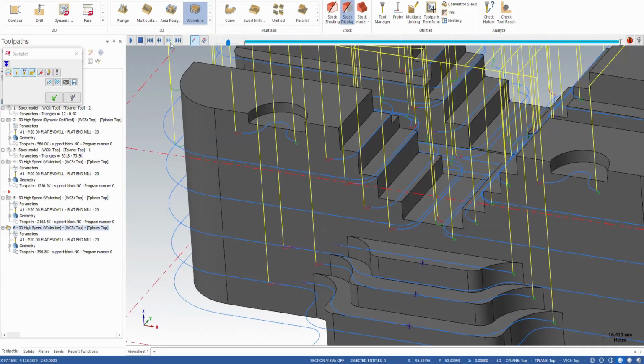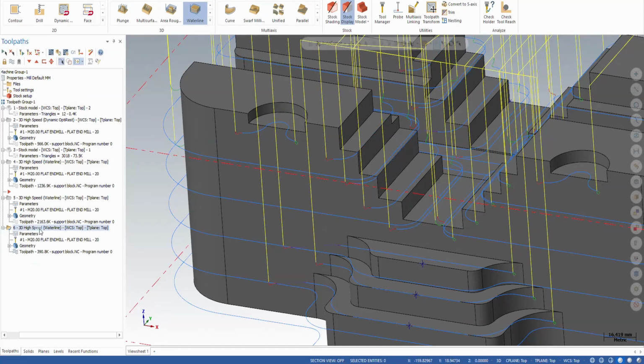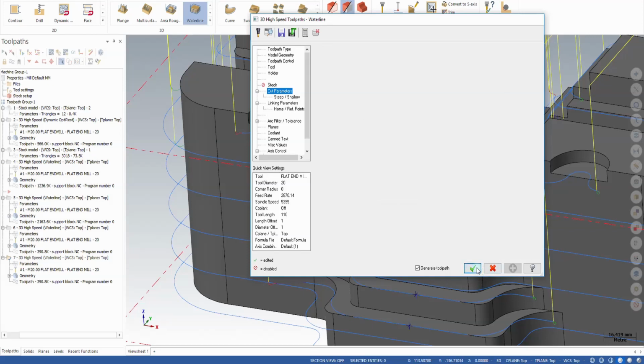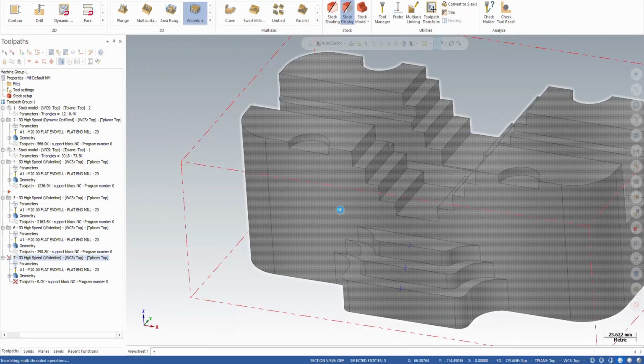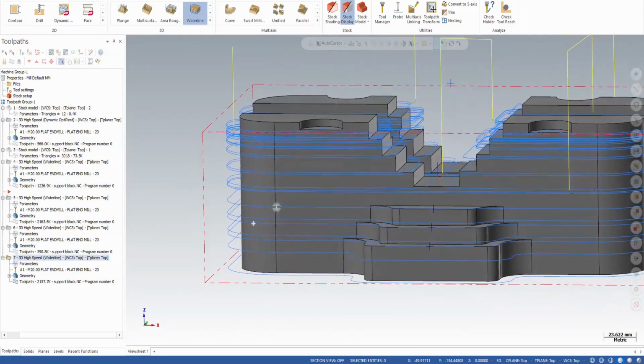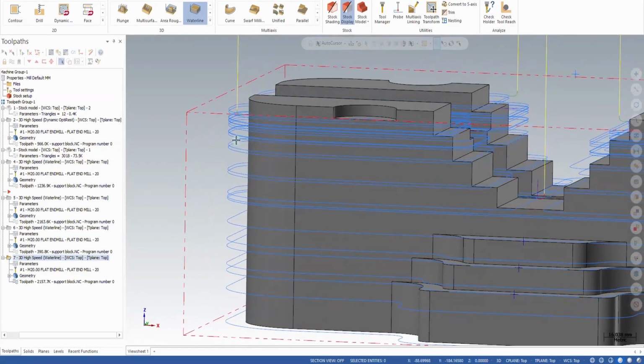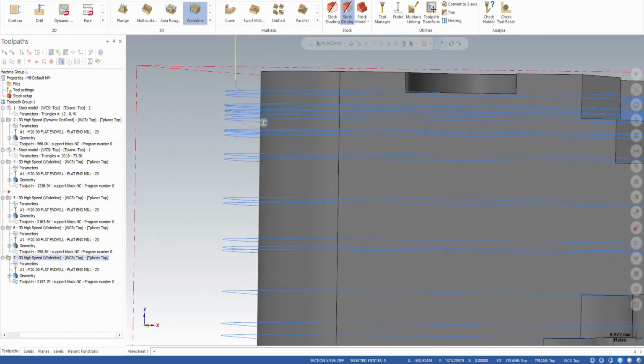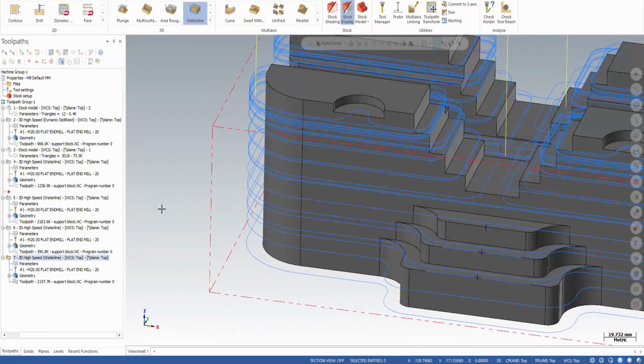Look at this. Next on our list is flats only, and what it does is Mastercam will switch off step downs and use only flat areas to generate the pass around the whole part. Look at this. And the passes around the whole 3D model in those flat depths.